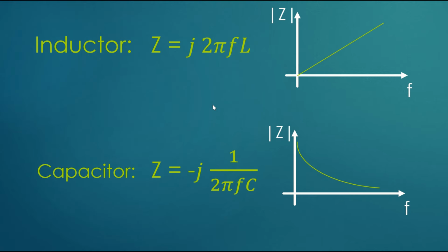All right, an inductor has an impedance Z, which has this equation. Basically, it's proportional to frequency. The larger F is here, the larger Z will be. And the proportionality constant is the inductance itself. There's always 2 pi's floating around in the world, so the equation is actually 2 pi FL.